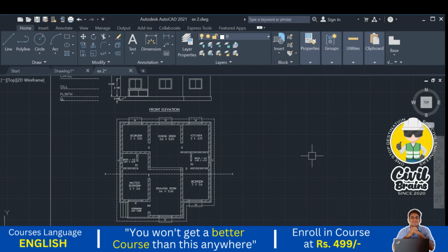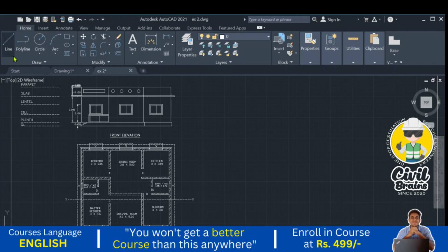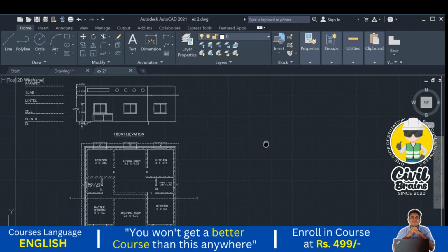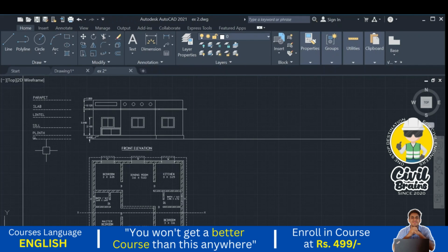So how do we start the cross section? The first thing is we need to draw the ground line. Whatever the ground line is, I project that same ground line so that it will be easy to draw. So I projected the ground line. The next step is we need to identify the levels, the same as we did in the front elevation. In the cross section, not only the superstructure and the roof, we need to identify the levels of the ground also. Below the ground also, whatever will be there, we need to identify. Okay, so I just open the text.